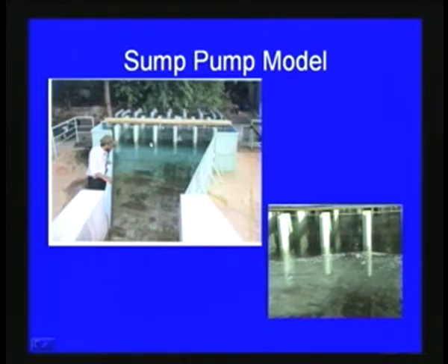As I mentioned, theoretical development or application of theory or mathematical modeling is very difficult in this kind of problem, like the sump pump. But if a good model is developed, then you can see all the turbulence and easily identify all the problems with respect to the sump. This model has been built based upon Froude number similarity, and we used a scaling of 1:8, and we found that the existing design is okay.